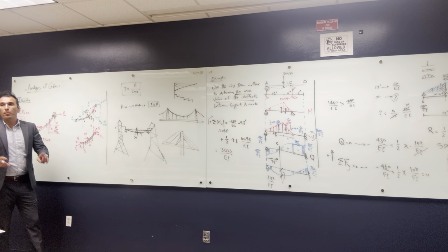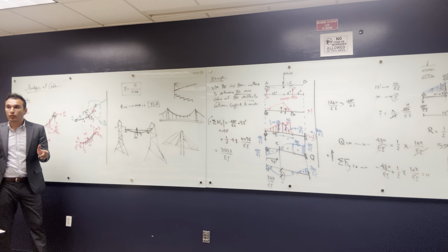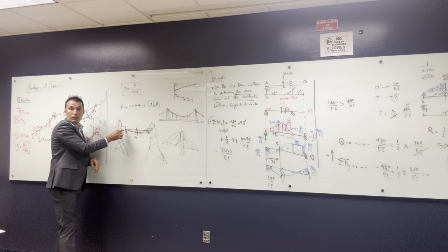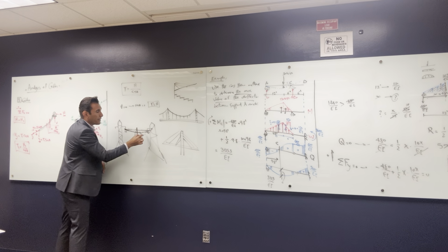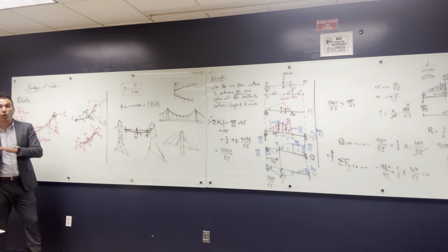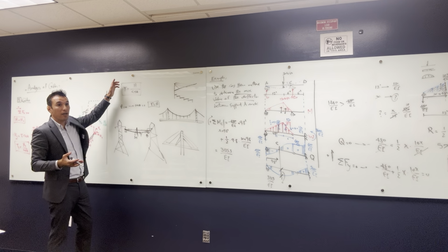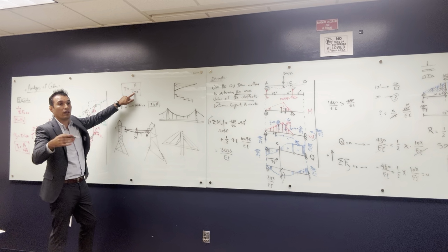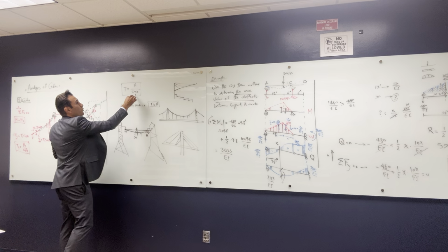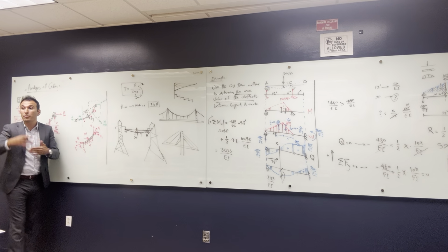That's right. But let me ask you, what is the maximum value of the tension? Where is it gonna be? Where theta is much bigger. So it's gonna be here at the support. So here is the maximum tension, at the support. Why? Because that is where theta is bigger. Once theta is getting bigger, this number is getting smaller than 1. It's gonna be 1/2 or 1/3. So it's gonna be 1/2, so this horizontal is gonna be multiplied by 2. So it's gonna be much bigger.